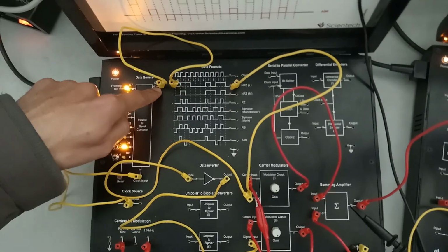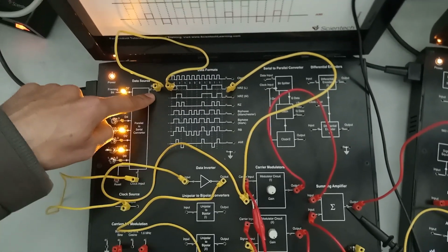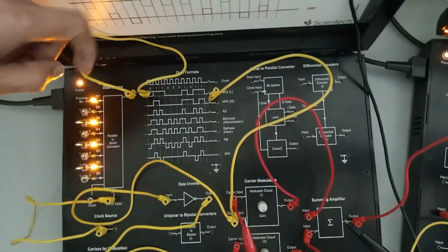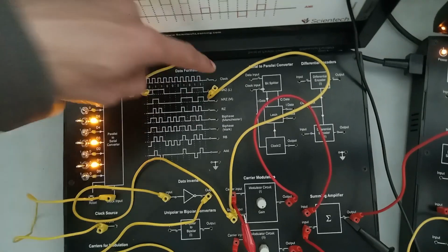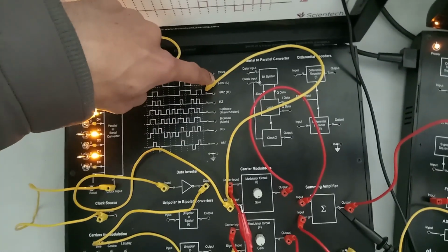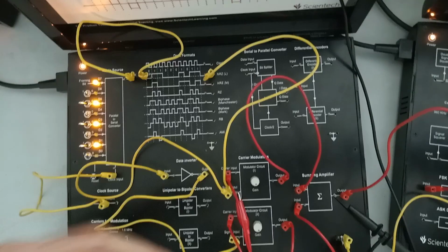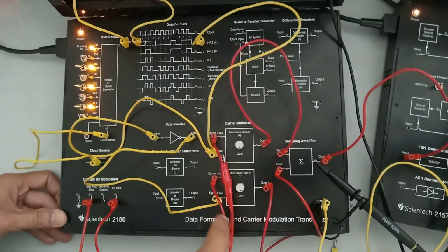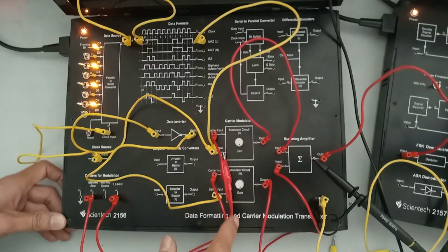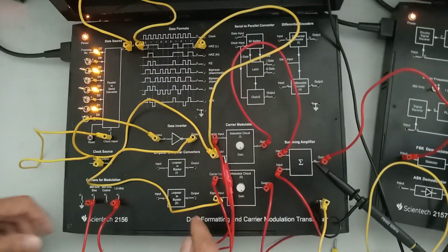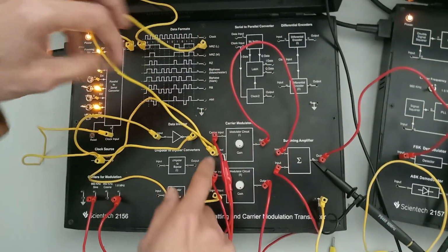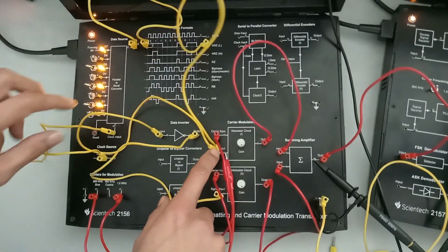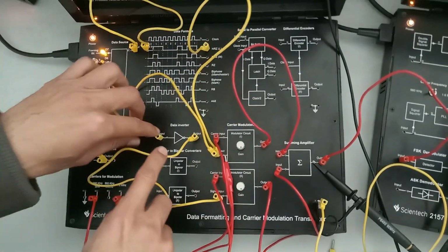This uncoded digital data is fed to the line coding. For line coding we have chosen NRZ-L. So here we will get NRZ-L data, which we take as input to our FSK modulator. The FSK modulator is realized through two modulators. For one modulator we give the generated data without any modification, and for the second modulator we give the inverted form of this data.